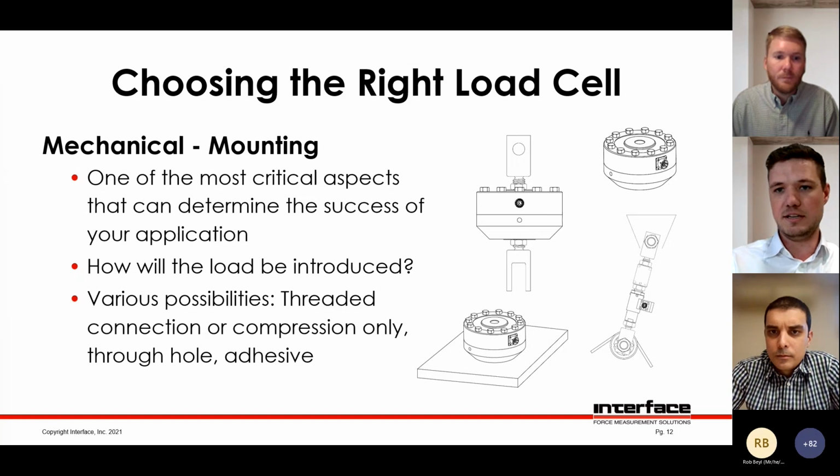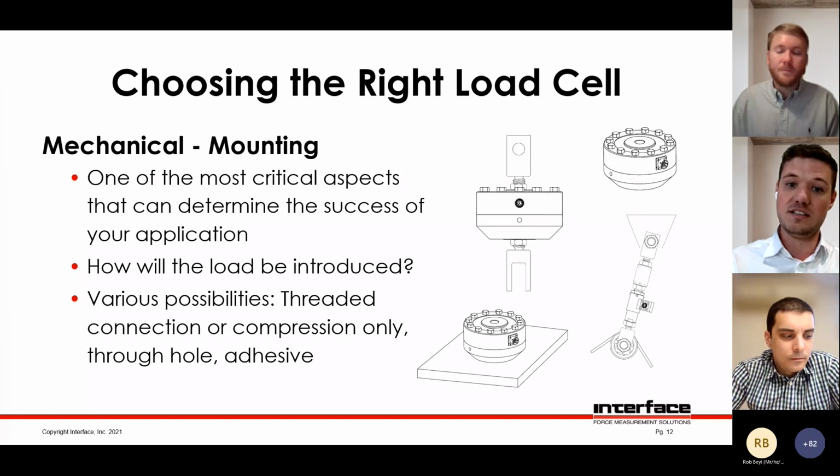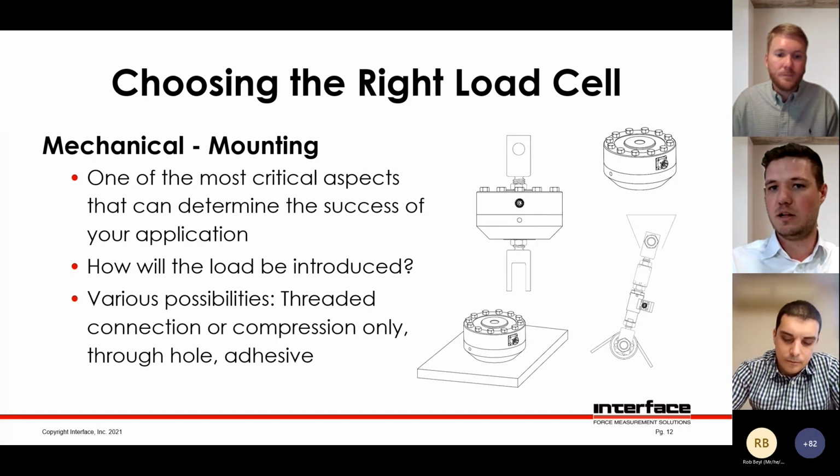And it's a great thing to discuss with the application engineer how the load will be introduced, be it clevis or threaded rods or rod ends or domed surface for a button or adhesive, or there's very many options. So knowing that in advance will help us specify the right load cell for your application.